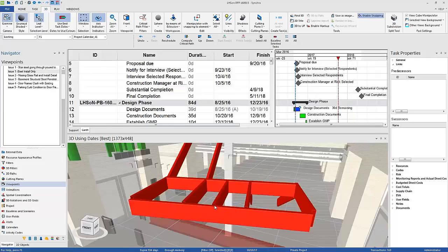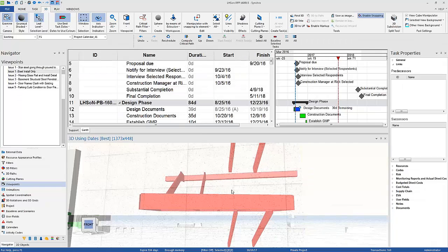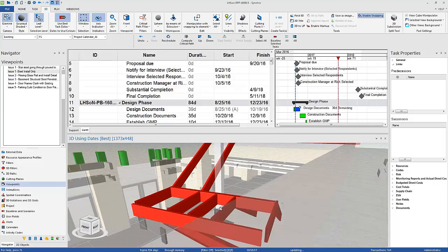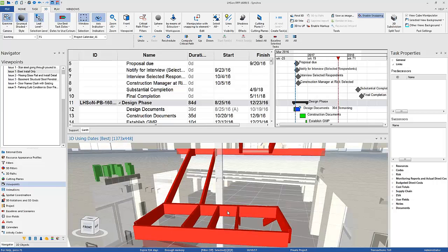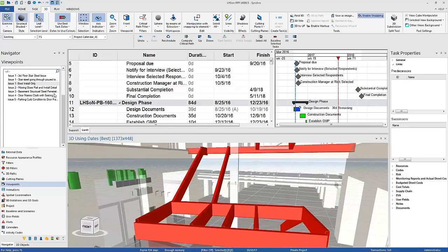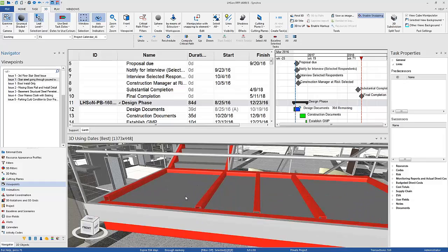So here is stair steel. And you can see the stair steel is obviously to support a monumental stair that's in the atrium of this building. Now the issue here, it looks fine right now, but as you start investigating the stair, when I activate that selected view, you can see that the tube steel is coming through the finished floor.